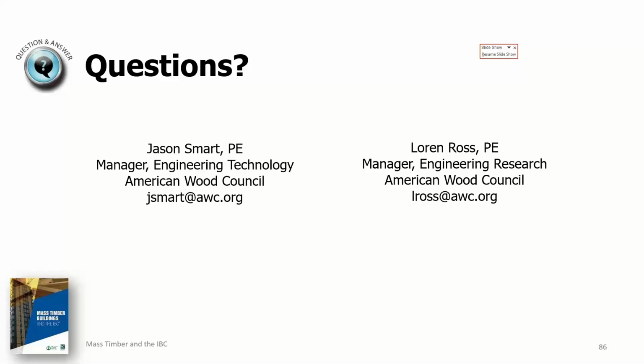Yes, it does affect vibration, because obviously vibration is a function of both mass, span, and stiffness. By adding mass without proportionally increasing the stiffness, you're going to wind up decreasing the natural frequency of that span. And so yes, that could bring you down into the range of vibration frequencies that is considered annoying from a human factors standpoint. And yes, there are resources available for addressing the vibration.